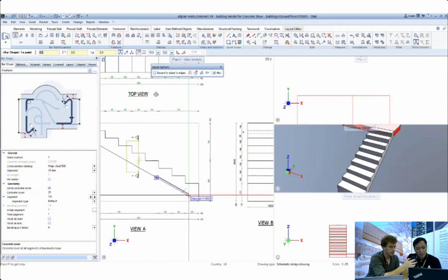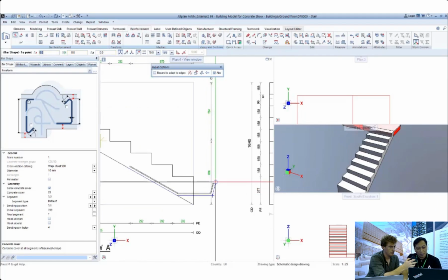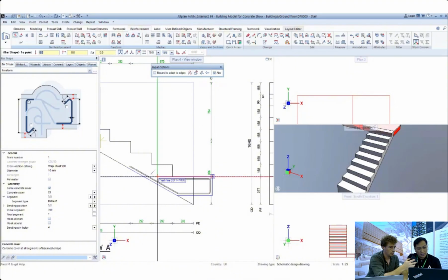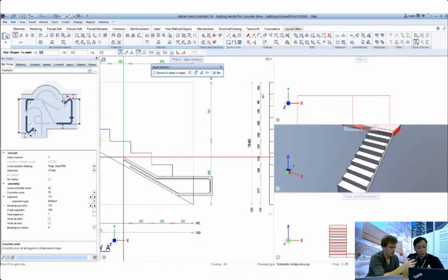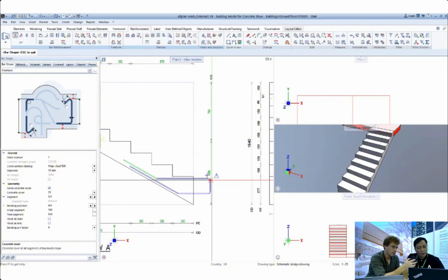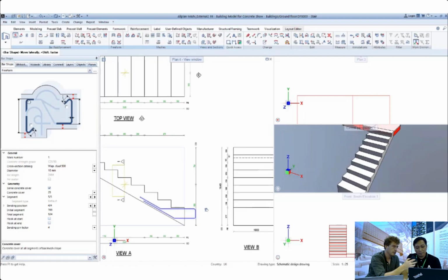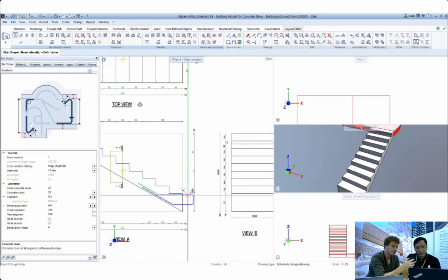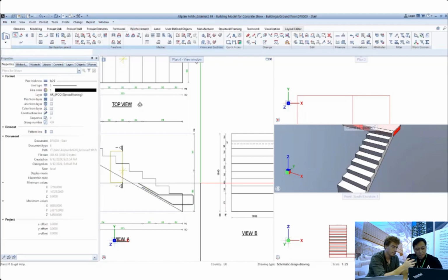Yeah. Right, so just creating the shape of the reinforcement. Somewhere I can just put some tracking line like this, and then say onto here, somewhere here, and then I can just terminate, or I can continue. So maybe I can just continue something like this and then escape. Yeah. So you already have the profile, right? Of course, it's not yet done. You have to place it correctly. So I just right click and then place bar shape. And then you have the option here to define.